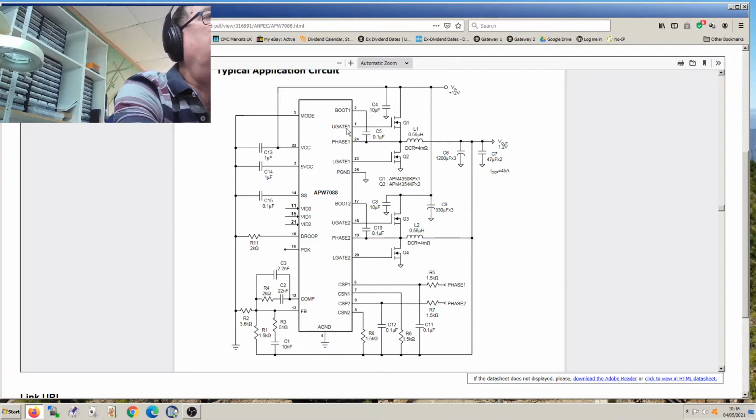So the only real way now, we've already removed that. So we know there's no path to ground here. That's what I did yesterday. We know there's no path to ground there because we've removed them. So the only way to prove now is it here, or is it on the GPU or the RAM, the 9 or 10 ohms? Is either to remove the chip or remove the coils. Yeah? So if we take the coil out, then we've broken the circuit from here to the chip.